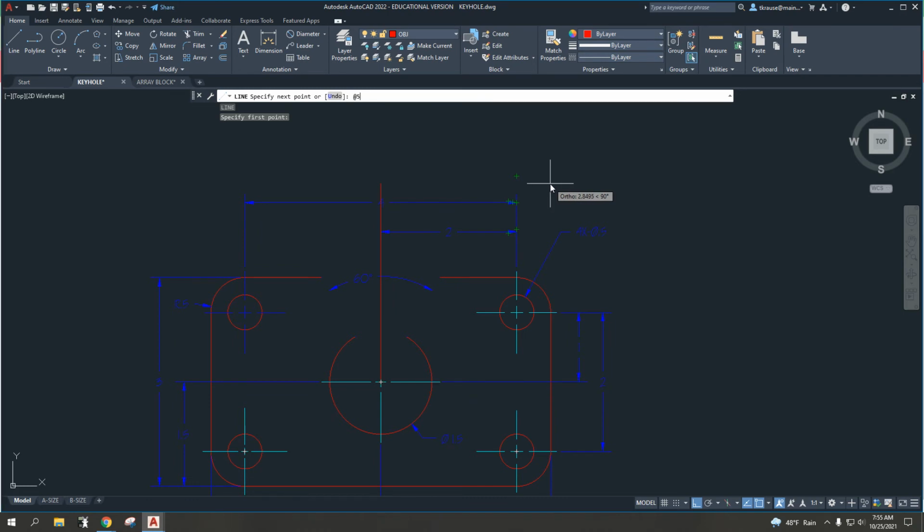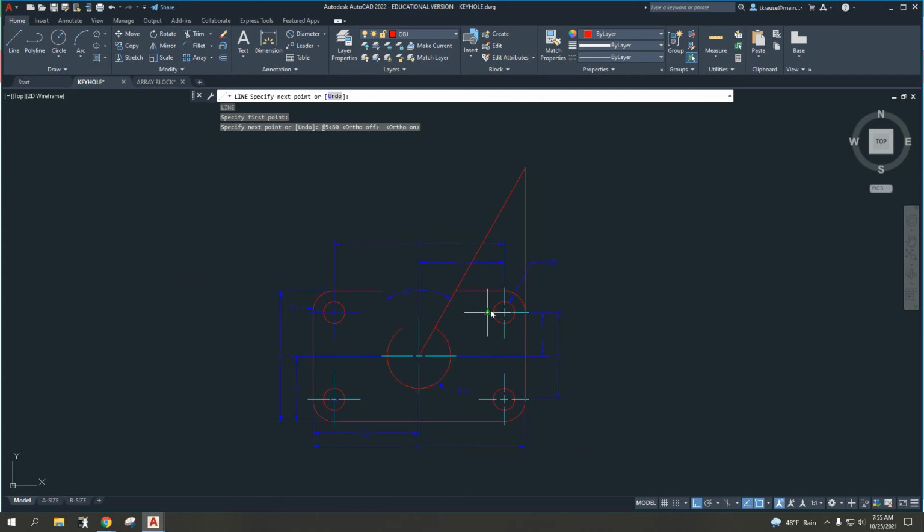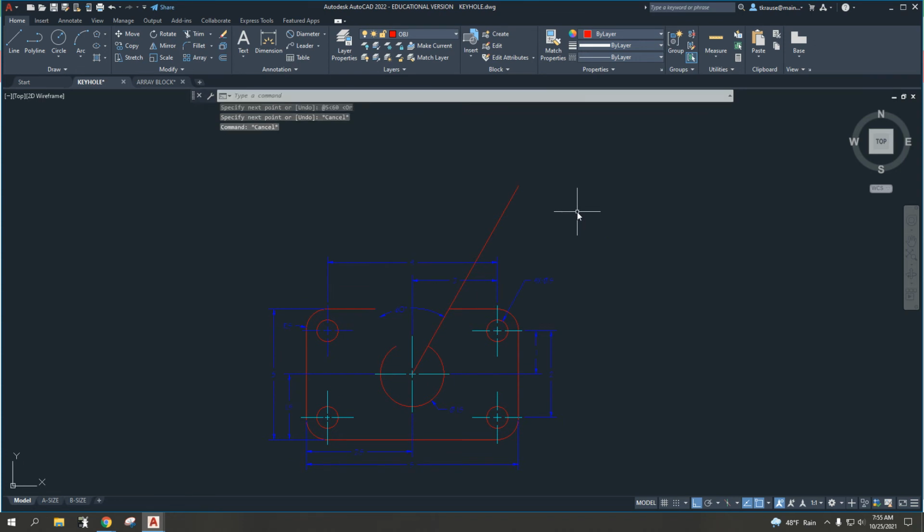So I'm going to do Shift, comma, which is the open alligator. And in this case, I'm going to do 60. Okay, because we talked about we want this to be at a 60-degree angle. I'm going to hit enter. Okay, and you'll see that I now have this line coming out, and it's 5 inches in length, and it is at the 60-degree angle.